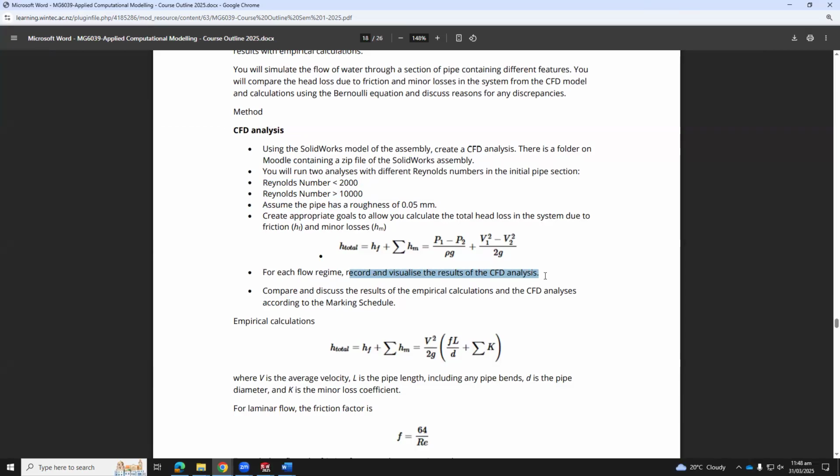First you set up your velocity. Now I'm giving you the Reynolds number. You need to think about the velocity. You calculate the diameter; you reverse the equations. Reynolds number equals what? Rho V D over mu. You have Reynolds. You set it, for example, 2,100, or sorry, less than 2,000. Let's set it 1,000. Rho, what is the fluid here?